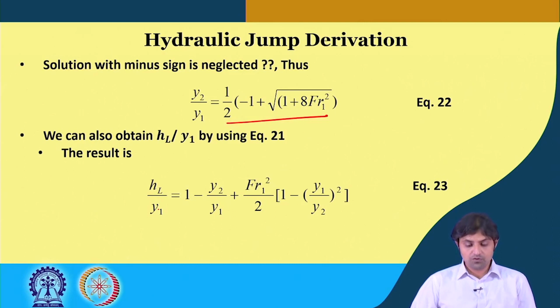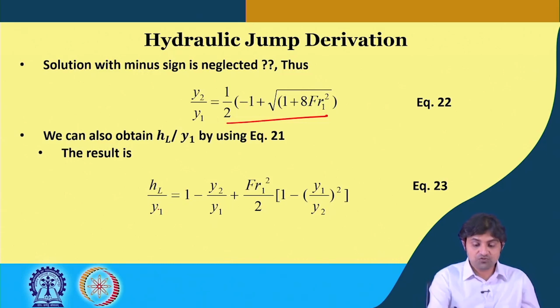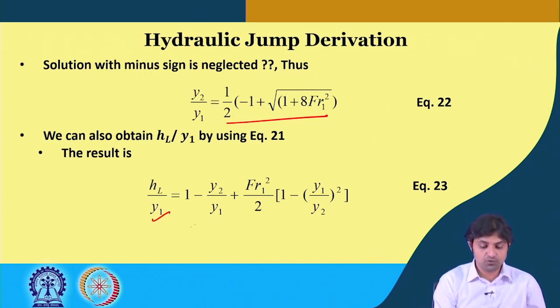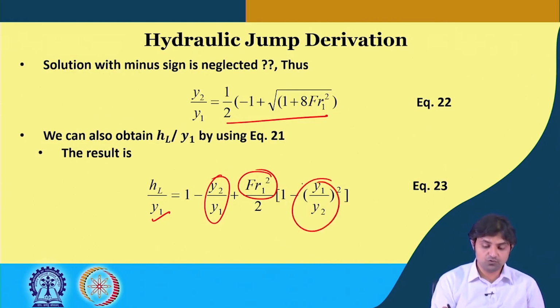We would want to find out the situation after the hydraulic jump has occurred. So, in most of the cases y2 and v2 and those things are unknown. So, y1 is known. Using this formula we can also find y2 or y2 by y1. So, Froude number at 1 is known. If we know everything at section 1, Froude number at 1 is also known.